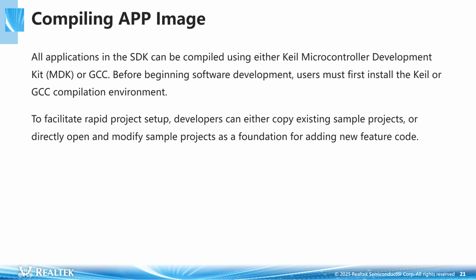All applications in the SDK can be compiled using either Keil or GCC. When using Keil for compilation, please note that different ICs require different versions of the compiler. You can refer to the instructions on page 6 for more details.